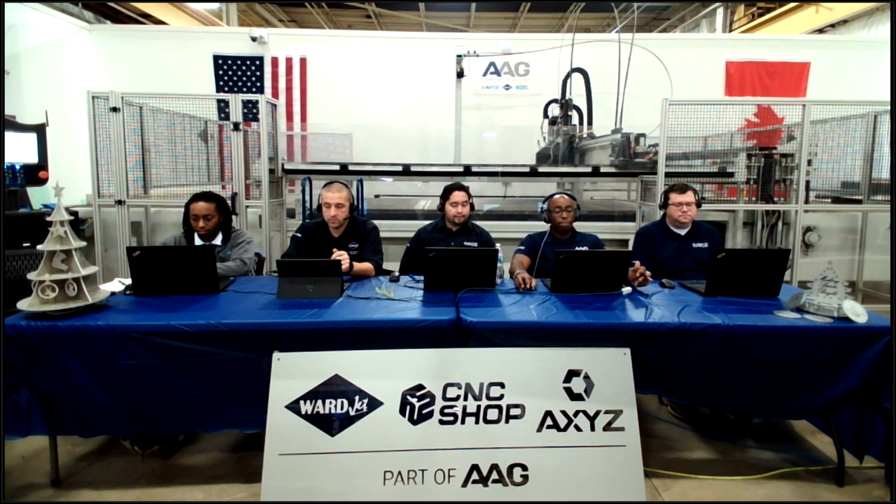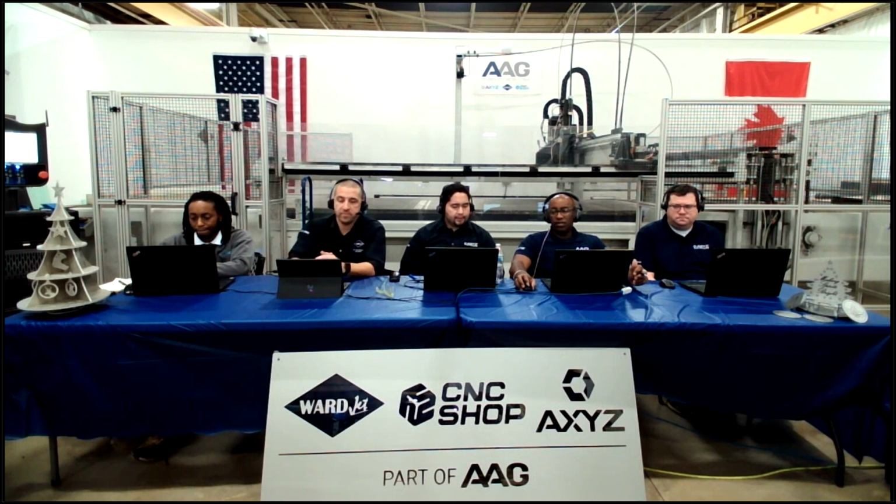You still use, I think, about a 3/8 tool, depending on the thicknesses that you are working with, but anything 1 inch thick and below, we typically like to keep that as a 3/8 tool. 1/4 inch seems to chatter up a little bit too much, especially at longer lengths. Feed rate wise, Noel, I'd say about 200 inches per minute. Okay. All right. Thanks, Kevin.